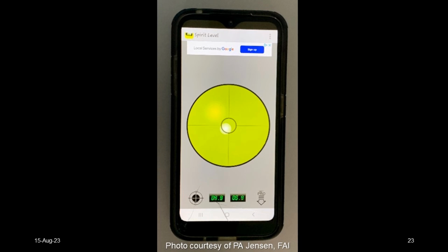Level. I said bring a level. Where can you find a level? Quite often you can find one on your phone. There are many different apps for levels, and what we're doing here is a bubble level. So when I do an installation, I try to set the fixture, not the louvers, but the fixture itself, parallel to the ground. And then if we need to adjust it up or down, we can. But to have a uniform starting point, that's where we start.